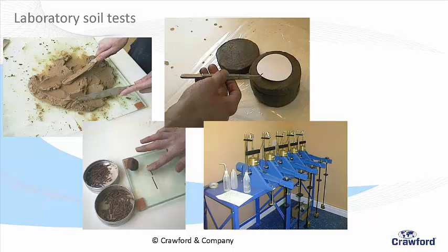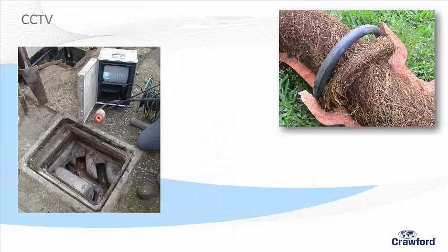We call it dirty videos. The other thing we do, because the third parties might say, aha, but the drains are going to cause the damage. The drains do sometimes cause the damage, but usually they are a symptom of the damage, not the cause of the damage.